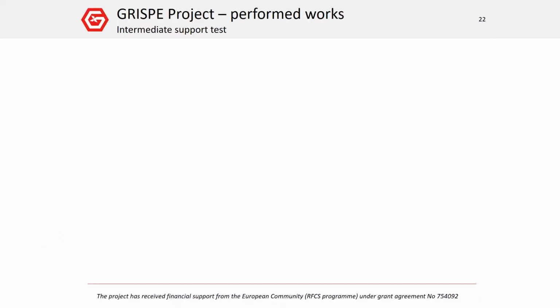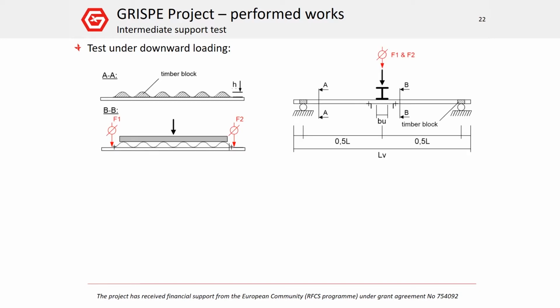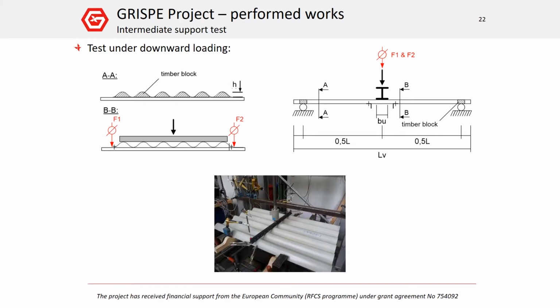To study the load-bearing behavior at an intermediate support, that is to say to determine the design resistance moment on support and the support resistance, 3-point bending tests were carried out according to Eurocode 3-1-3. This test consists of simulating an intermediate support by applying a line load presenting a width corresponding to the width of this support. In such a configuration, the test specimen is in the opposite position and a device constituted of steel plates simulates the transversal continuity of profiles.